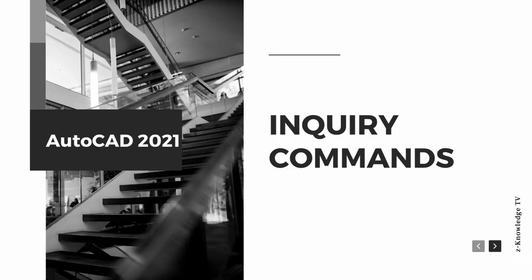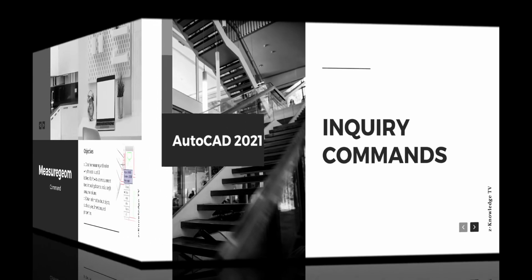Okay, in this video, ating pag-aaralan kung paano gamitin ang Measuregeom command and other inquiry commands to obtain geometric information on objects in your drawing. As you create objects, the defining points and object types are stored in the drawing database. So, pwede natin gamitin yung command sa inquiry toolbar to retrieve this information or to obtain distances, angles, areas, object types, and other important data for your objects.